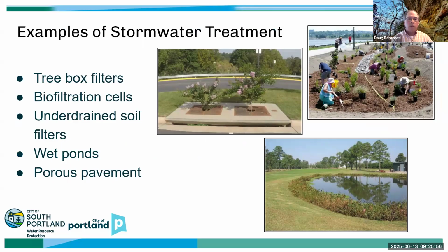Okay, so what are examples of stormwater treatment? You can look at the traditional setup: you've got a catch basin with a pipe and then it goes out. That's not being treated. So any pollution coming off the landscape that enters that catch basin is not being treated. There are a variety of what we call gray infrastructure, traditional types of things that help remove trash, floatable materials, and sediment. But then we have more modern green stormwater infrastructure that we're putting in now, and they include a plant and/or a soil biological mechanism.